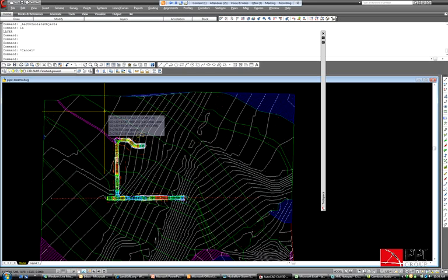So the ability to real quickly, just through a label style, what we did there is just went into our label style into the display tab and turned on some watershed features, and then we're able to use the surface tools to extract those objects off the surface. And once that was done, we had them within parcels, and like I was saying, you're then able to quickly create tables from that and communicate with other programs, primarily through SDF. You could also come out through the HydroFlow that's now available, shipping with Civil 3D. You can come out with those parcels and use them as a background as you're laying out your pipe runs.